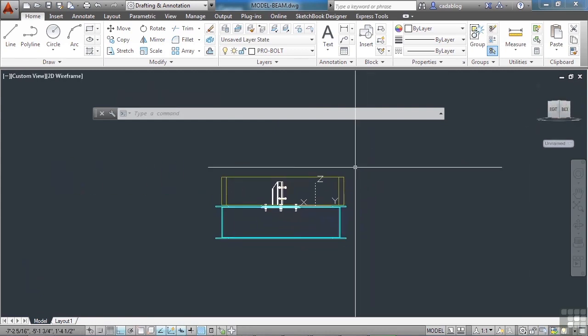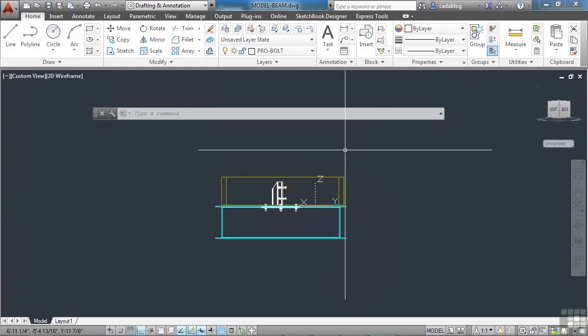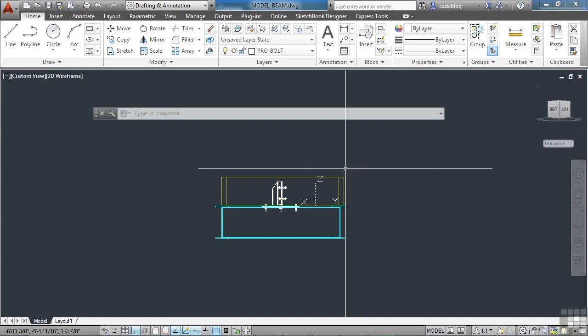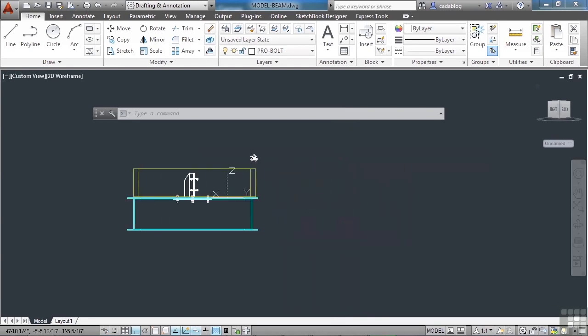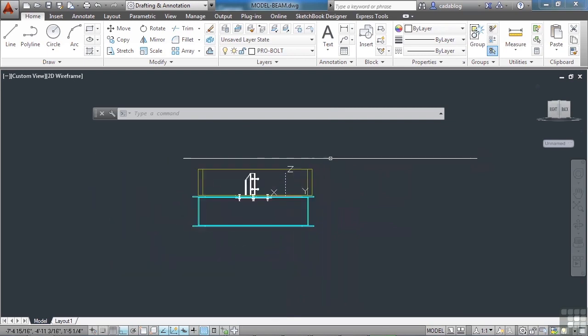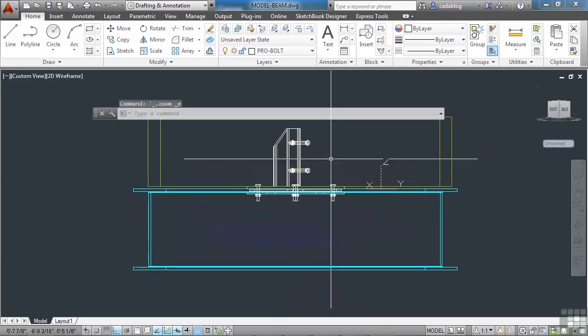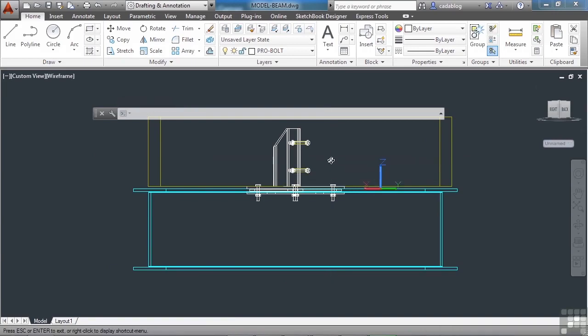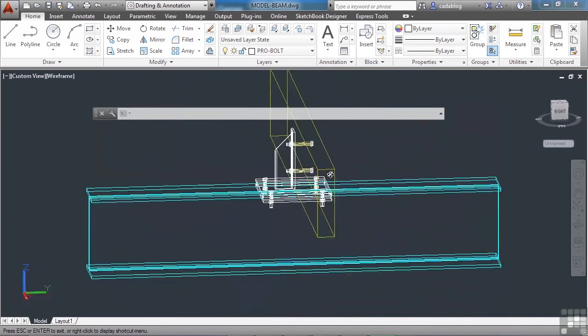So these are a lot of the different navigational tools that are available to you in AutoCAD. A lot of them are very advanced. Some of them are very tricky to use. You're going to find that your mouse will be just about all you need for about 90–95% of your navigational needs. Click and hold the scroll wheel and you can pan around. Zoom in and out by just rolling the wheel. Double click it, that's a zoom extents. Hold your shift key and your middle mouse button, the scroll wheel button, and move around, and there's a quick orbit.